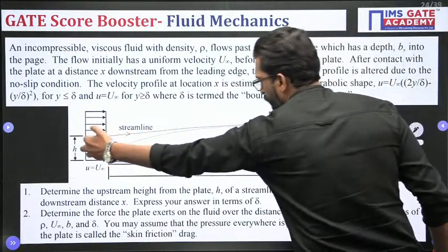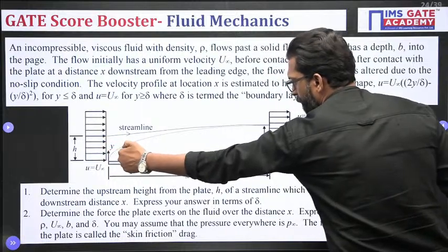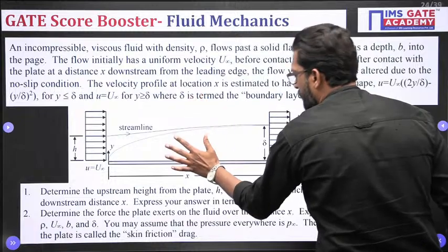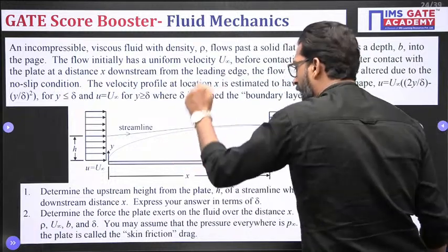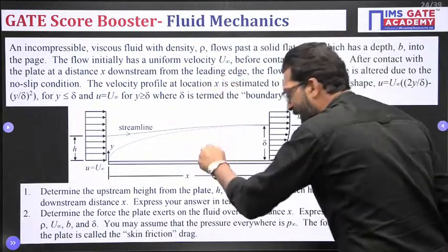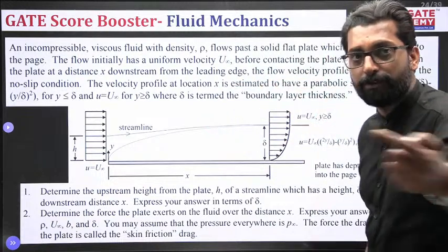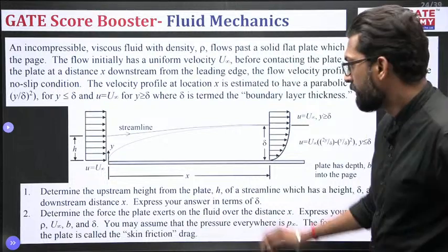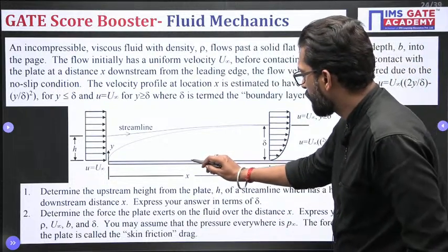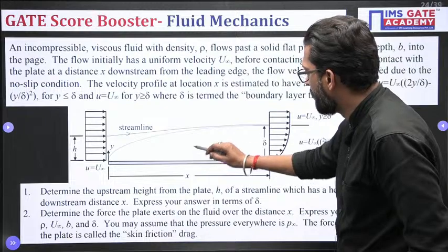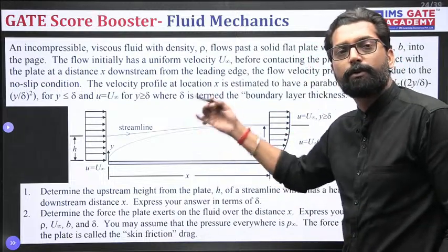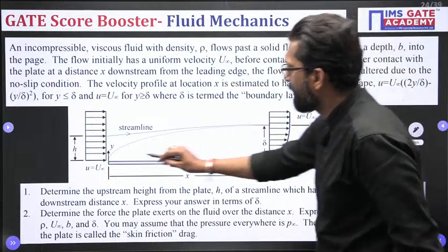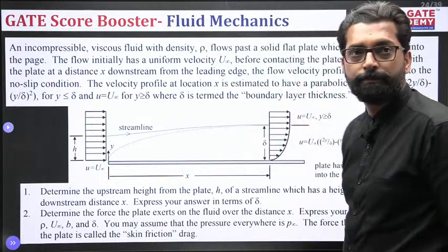That means if the fluid is flowing from a free stream, due to the no slip condition, the fluid on the plate at that point has zero tangential velocity along the plate direction, zero relative tangential velocity. So there is momentum diffusion from the plate to the fluid in the perpendicular direction. So due to the momentum diffusion, there must be boundary layer growth.